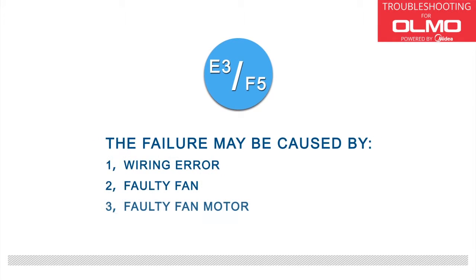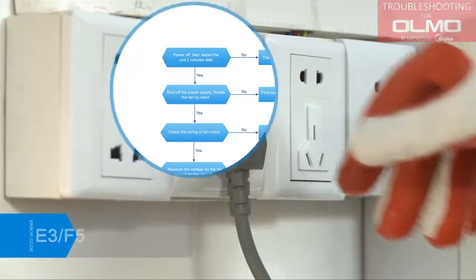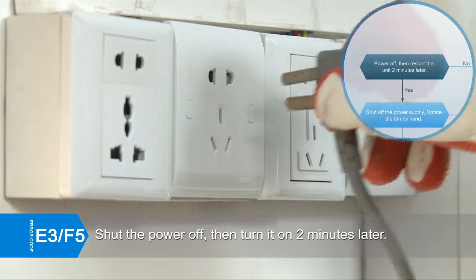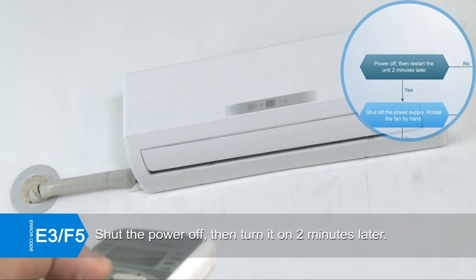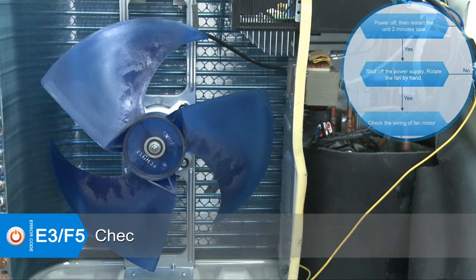The failure may be caused by: 1. Wiring error. 2. Faulty fan. 3. Faulty fan motor. 4. Faulty main PCB board. Shut the power off, then turn it on 2 minutes later. If the error still exists, shut the power off, then check the fan.